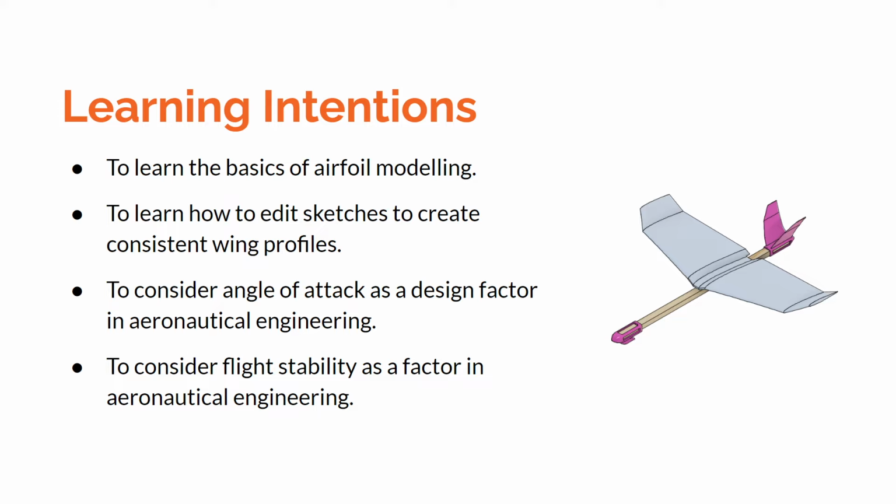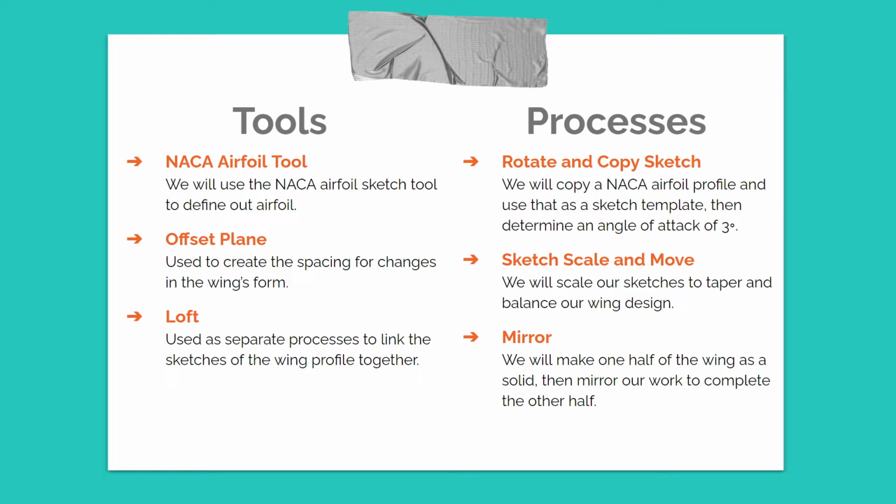So the tools we're going to be using: the NACA airfoil tool, which I've shown you all how to download and where. The offset plane tool, we're going to be offsetting all of our planes before we actually start applying our sketches, and that will be where we apply our airfoil sketches, then we'll resize them and move them around.